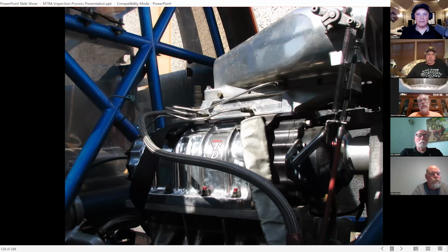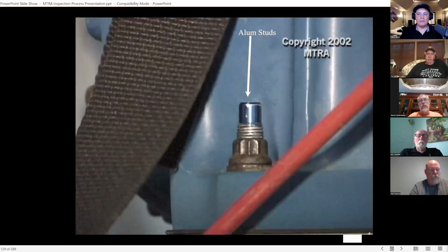In our case, it doesn't happen very often, but when it does, we're protected. These blower restraint straps in this picture have silver sleeves on them. Fire resistant sleeves are quite common in drag racing, not so common in monster trucks. You'll see them because people buy them, so you might want to slide them out of the way to get a look at the straps underneath.